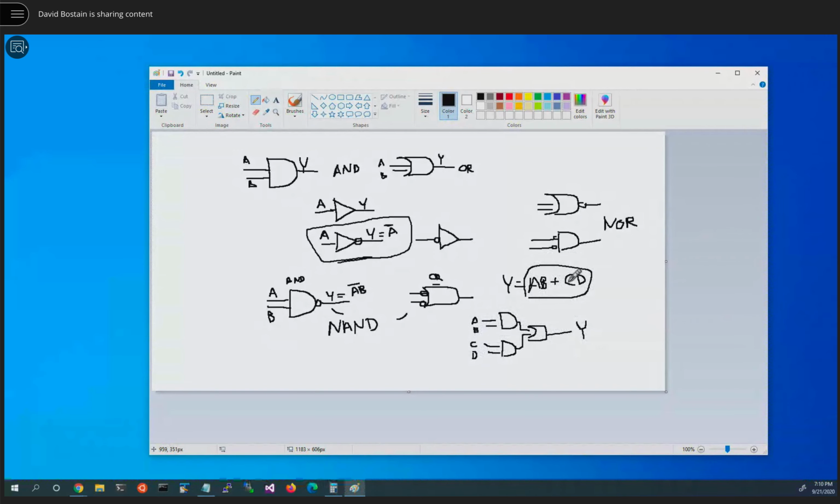4 inputs, so it's one of 64K or 65,536 different possible functions. But we can tell here that in that table, there are only 2 min terms available. We know the first term here is everywhere A and B are 1. We know the second term is in the truth table everywhere C and D are 1. So that stands for multiple lines. This is a reduced equation, which we'll talk a lot about in the next session. Does anybody have any questions about what we've just covered tonight before we change topics?